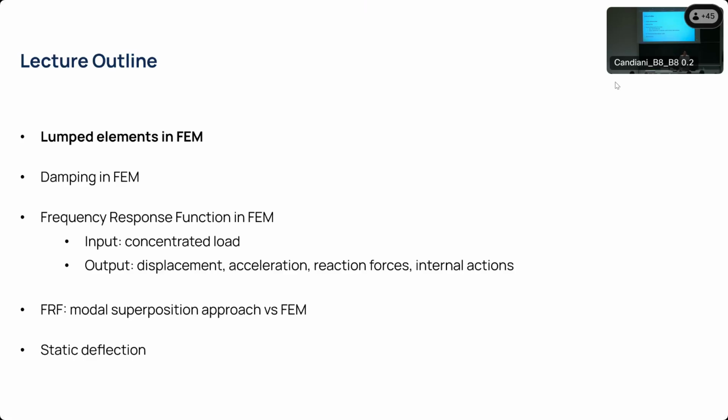So we will see how to use all the frameworks, all the code you have, to compute a frequency response function between an input, which is always a harmonic force, and an output, which can be a displacement, an acceleration, a reaction force, or an internal action. So we have those different options, and we will see how to model them. And lastly, we will see how we can also use a modal superposition approach, which reminds me of something we've already done in class, I hope.